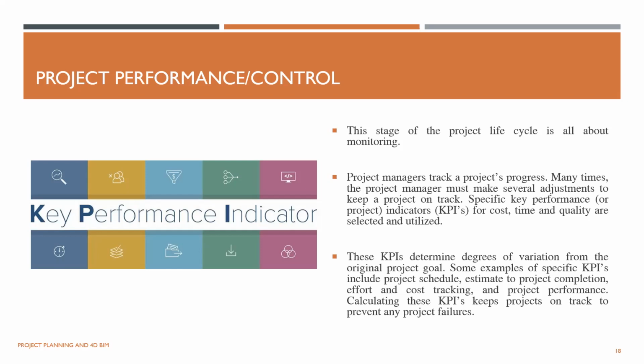During that time, because we couldn't get the material on time, it is very difficult to get the reinforcement bars and the cement, so automatically the delay will happen. In that time, we will start to track based on that particular plan. We will have a baseline and we'll start to track what is the delay, how many days of delay we got, what is the reason for that, and what are the final outputs.